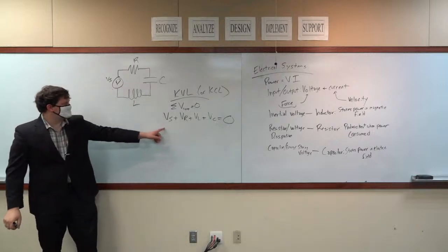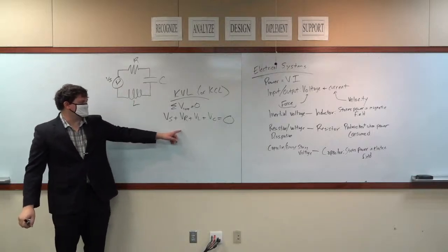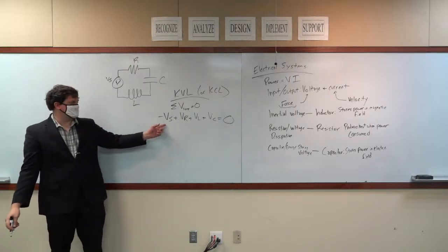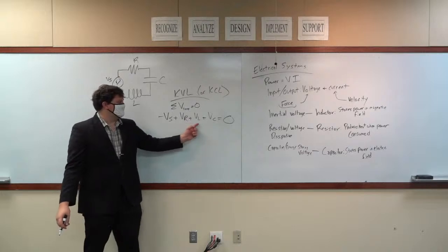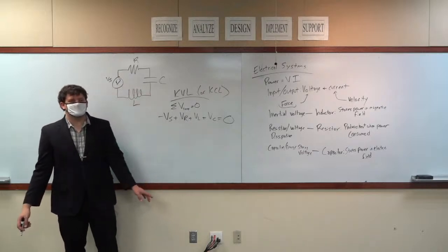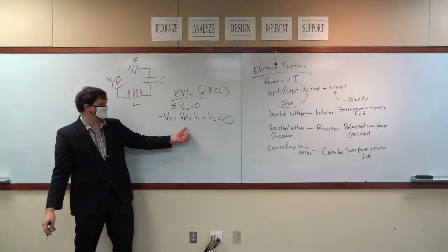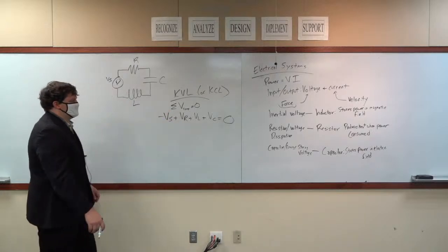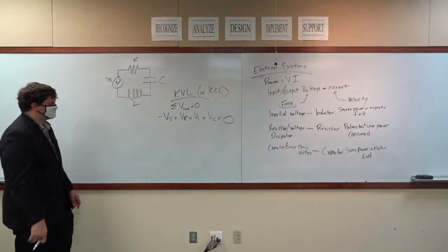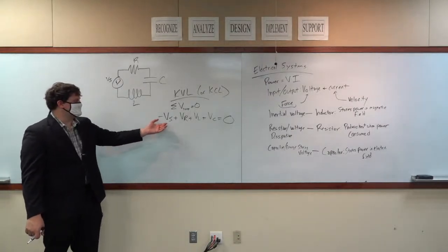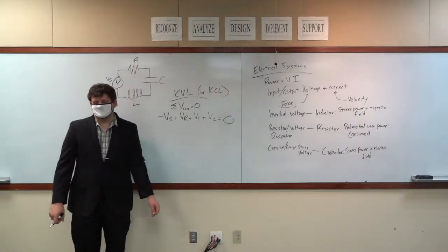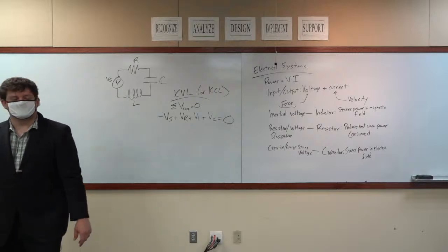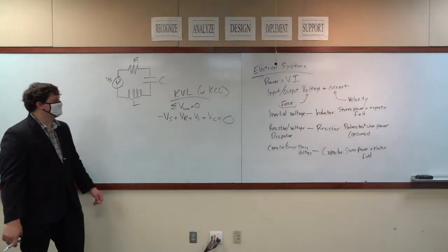The voltage across the source plus voltage across the resistor, which I'm going to go ahead and make negative just because that's sign conventions for KVL, Vr, Vl, Vc. And some people will do this reverse where Vs is positive and these three are negative because they're passive components, but whatever. This is how I learned it. Okay, so Vs produces power. These three consume power, and they all sum to 0. Sky is on his game today, because he totally got that one.